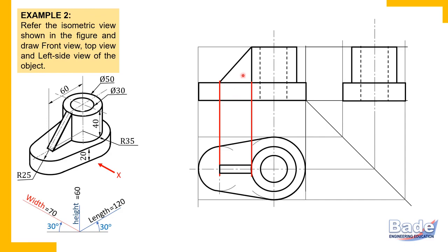Now remaining two views, this triangular plate appears a rectangular strip. It is a plate, so it appears thin strip. And what is thickness? We have assumed 10 millimeters. And thickness is to be measured parallel to width axis. Parallel to width. And in the top view, width is vertical. So measure width 10 millimeter.